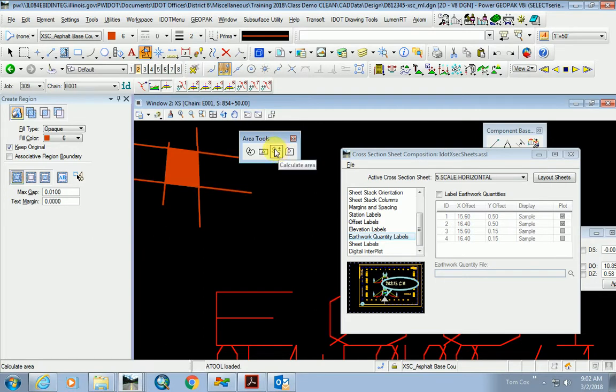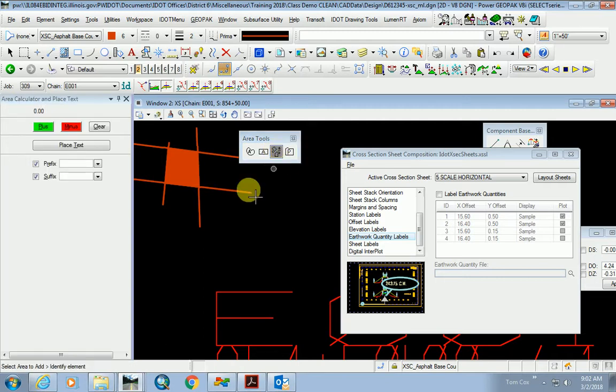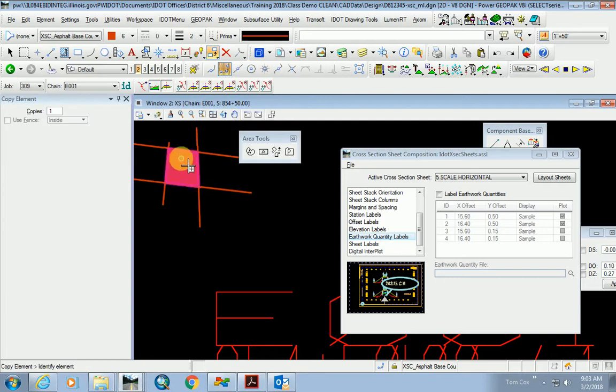What this does that the MicroStation version won't do is this. It allows you to have multiple shapes, and it will add the shapes together. So on your cuts and fills on cross sections, you're going to end up with multiple shapes, multiple cuts and fills, but you want to label the cross section with the cuts and fills in square feet, and that's adding all those shapes together. So let's just put two out there real quick, and I'll show you what I mean. You'll find this tool useful in a lot of areas when you're calculating quantities, not just cross sections.